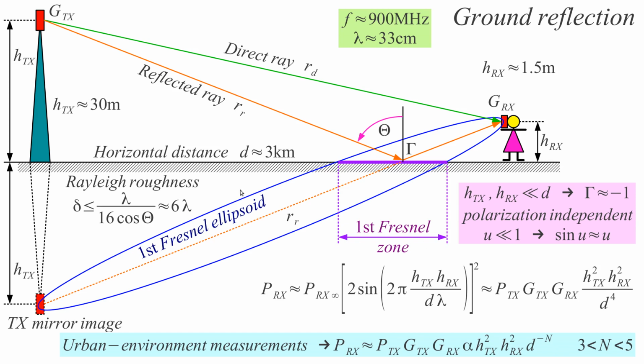This is the result where the direct ray from a base station to a pedestrian user here is unobstructed. There are no Fresnel zone lines in this direct ray, and there is no obstruction, and this pedestrian should have a good signal if he can see the base station. The problem here is the reflection of the ground, the reflection gamma of the ground.